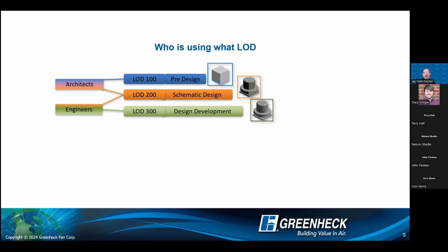Then there's LOD 300 in the design development phase. Now we're making selections of the products. We're creating schedules of equipment. We're doing electrical coordination. That type of stuff happens at that LOD 300 level.